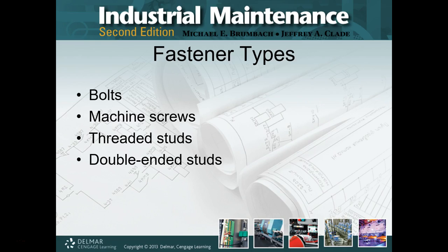So now you can easily take on and off nuts from that now trimmed all thread. You may still want to chamfer the edges of the threads so it's even easier, but definitely if you use the nuts to clean out the threads, your day will be a lot happier. The first time you forget to do that and try and cut and then put nuts on your cut all thread, you will be cussing the day. I've been there. I'm just trying to prevent some pain and frustration for you. That's all I'm trying to do.